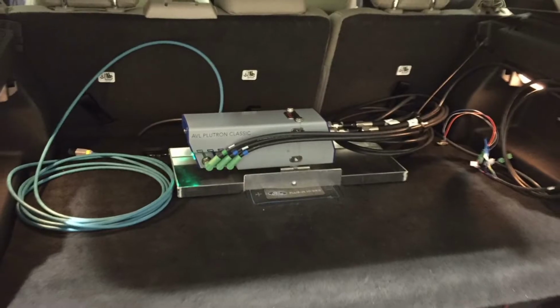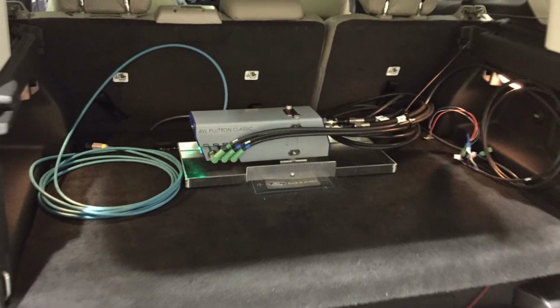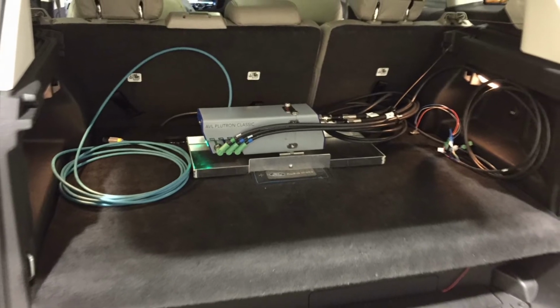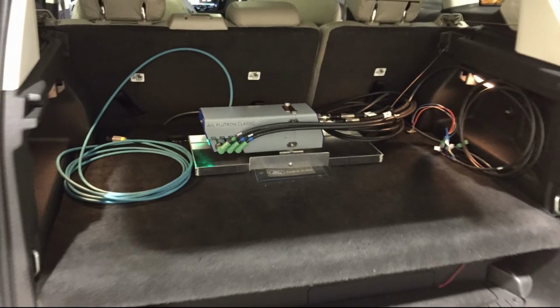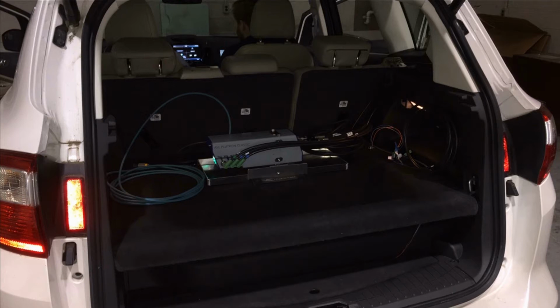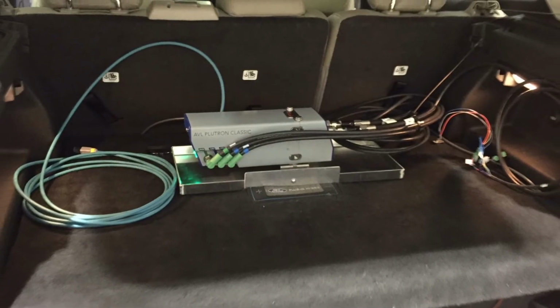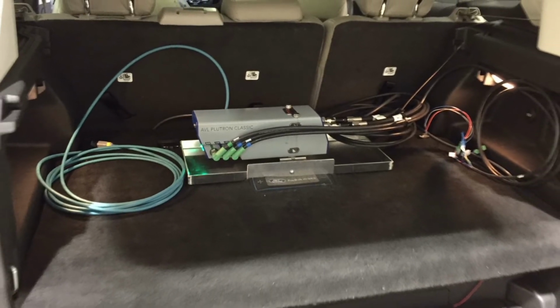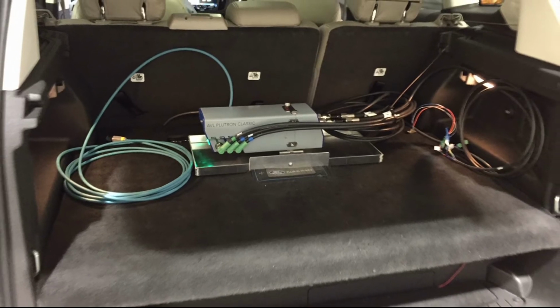An alternative position for the flow meter is in the trunk, for instance in case fuel lines inside the passenger compartment are not permitted. And in case there is no tank access from under the back seat, then the vehicle has to be inspected from underneath to find the quick connectors close to the tank module. The extra fuel lines to connect the flow meter will be somewhat longer, of course. This will increase the environmental influence and reduce flow rate signal dynamics a little, but average consumption measurement will still be accurate.